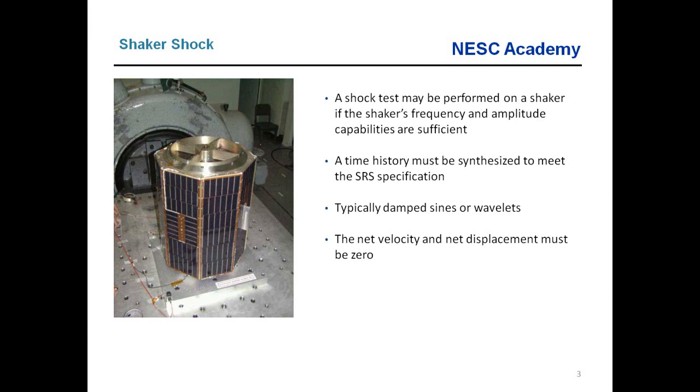So if we're going to do this shaker shock approach, we need a time history to satisfy the SRS. And there's at least two different candidate methods. I'll just mention two. We could use damped sinusoids or wavelets. Now, one of the requirements, regardless, is that the net velocity of our drive signal, the corresponding velocity to the drive signal, must have a net value of 0.